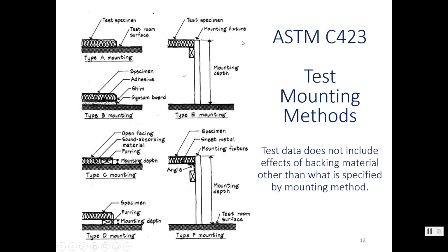Type E, this is typically a ceiling treatment. So usually there'll be E400. 400 millimeters is 16 inches, and that is the kind of rule of thumb for what a suspended ceiling is going to be suspended below the deck. So there'll be room for structure, there'll be room for ductwork, conduit, whatever else needs to be hidden in that particular space.